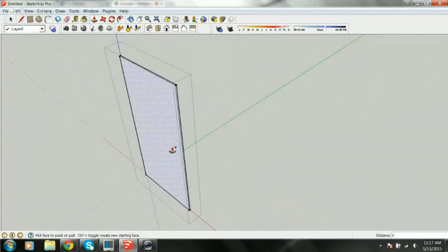Well, right. And the default in this distance button, you don't have to go down and type in it as the default. You can just type your numbers. For inches, you don't have to type the inches sign. Just type 3, 6, 9, 12, 24, 57, however many inches you want, and hit enter. While you're pressing the control button and pulling, you press 3 and it goes.